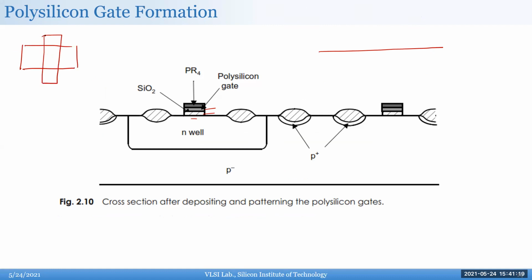Your first inclination, and in fact how people first did it, is that you take all the diffusion area which is not overlapped by the gate. So this is the gate area, and you create your P plus or N plus in those areas, the shaded areas. And then you create the thin oxide and poly separately.